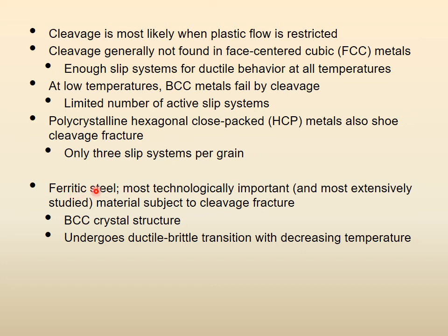Ferritic steel. Ferritic steel is a type of steel. Of course, mostly it is ferritic in nature, not austenitic and so on. It is the most technologically important and most extensively studied material subject to cleavage fracture, right? It has a BCC crystal structure and it undergoes ductile to brittle transition with decreasing temperature. So ferritic steel is most important to study cleavage fracture.